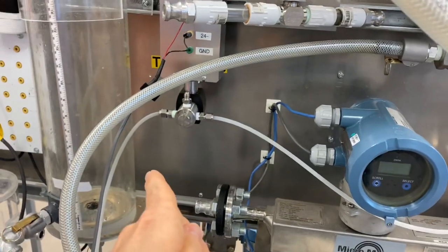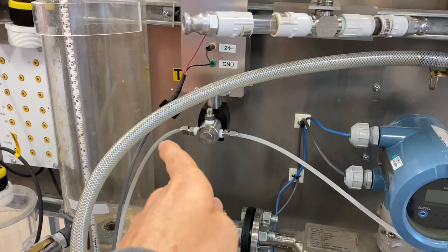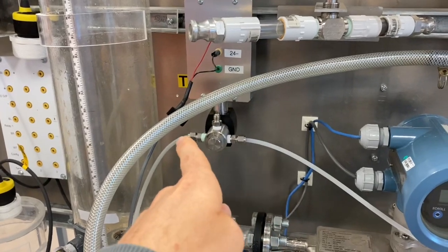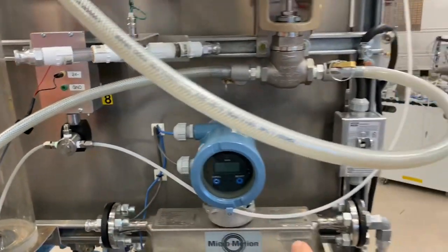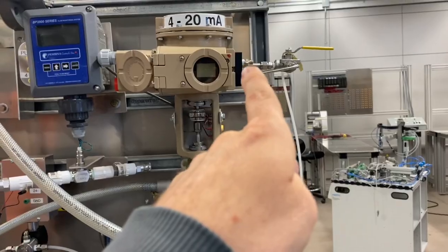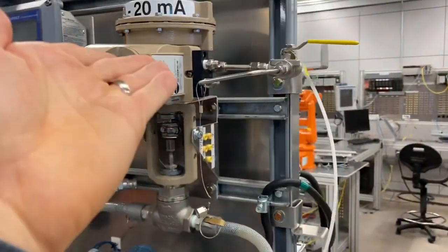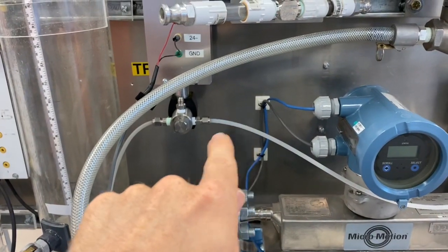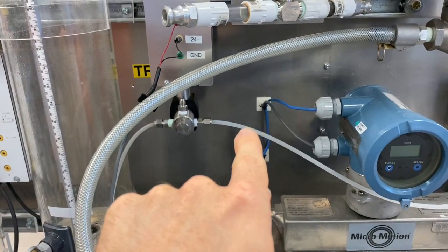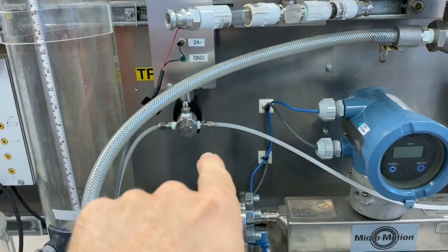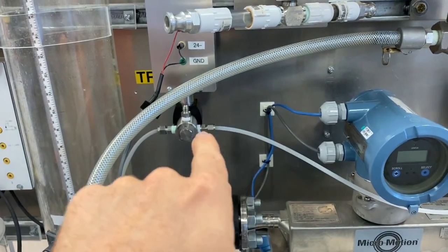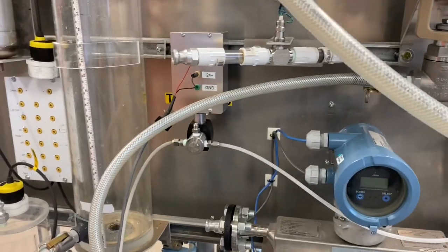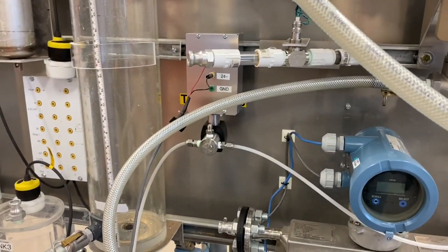What this solenoid does is we have air coming in here, and it's going to switch between these two ports. When the output's energized, air is going to flow out into our valve up top here and allow it to open. When it's de-energized, it's going to plug off this port and vent the air from this line out and allow the valve to close over here. So that's what's going to happen with our discrete output.